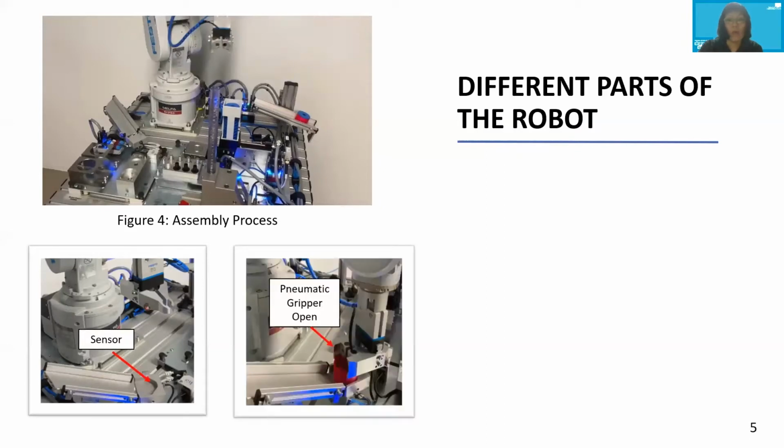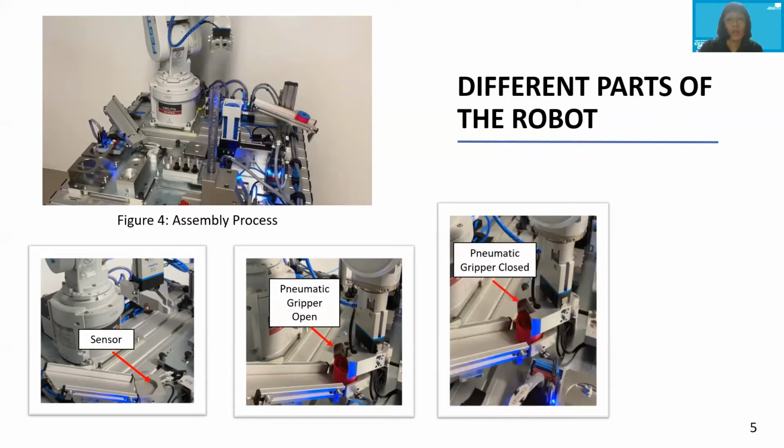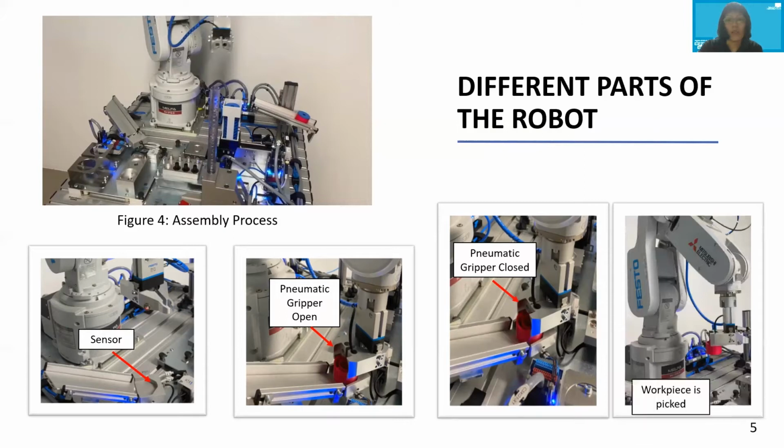The robot arm will then come down to the retainer teach position with its gripper open to pick up the workpiece. You will then close the gripper to hold the workpiece. Eventually, you will bring it to the assembly retainer module to assemble it with piston and spring. Do you know what is the operating mechanism of this gripper? Well, it is operated by Pneumatic Technology. So what is pneumatics? Pneumatic means air, and in this case, we are using compressed air. Later in the lesson, I will focus on pneumatic control.